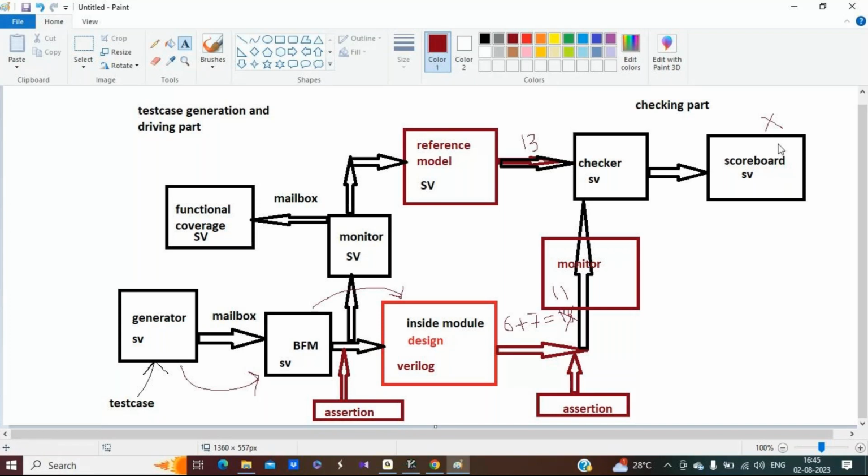We need this modularity for that. So each and every block knows what should be done by it. They will do their work only. The only thing we need to take care of is the different test cases. Different test cases will be driven and each block will do its work, and we need to check the scoreboard and functional coverage.